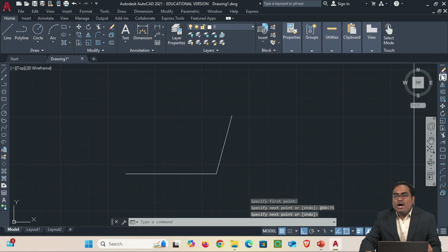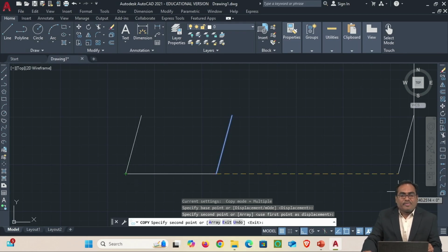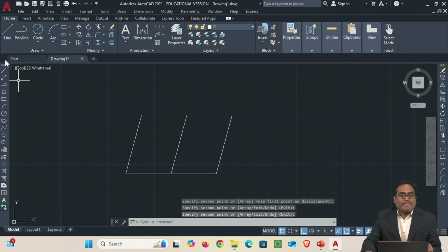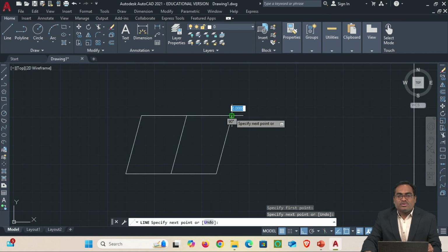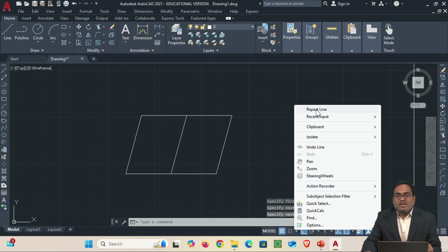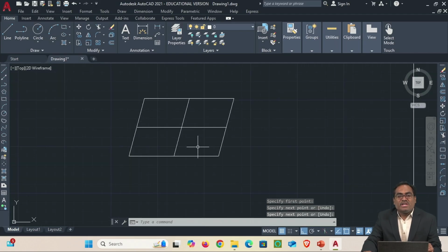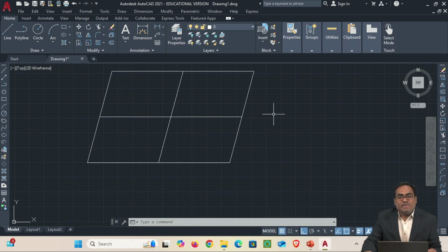So now what I can do, I'll go here and copy this one. I will not draw again. I will go here and copy in the middle also. Okay, I will keep it here also. Right, so this is the way I can complete the parallelogram. So I completed the parallelogram. Now if you want, you can give the notation: AB major axis, CD minor axis, EFGH parallelogram.